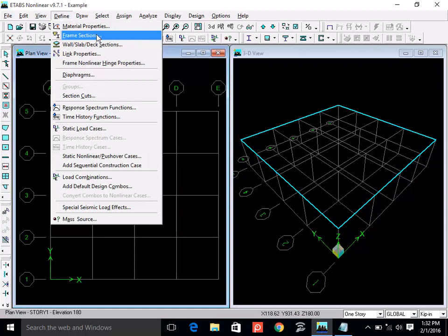So that the aggregates would pass. So these things are important for us. So in no case you go below 9 inches, but 12 inches is a very decent number to start. Right now, our spans were 15 feet. Okay, so I can define some beams 9 inches wide or 12 inches wide by 15 inches deep, or maybe 18 inches deep. This is the minimum requirement for deflection.